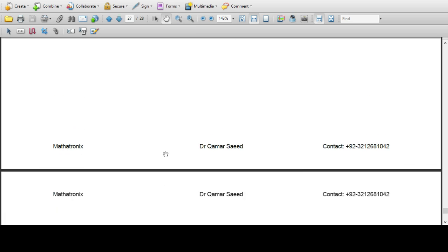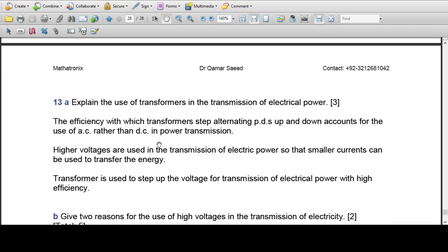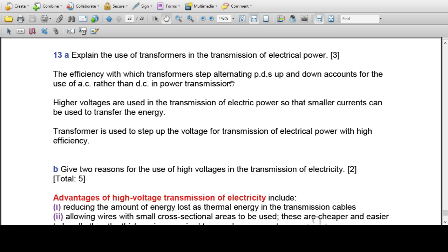A smaller current will be required to flow through the secondary side, the transmission will be easy, and a smaller conductor size will be required. Efficiency will be higher, and transmission losses will reduce significantly with the high voltage. This is one of the reasons we use the high voltage transmission system.